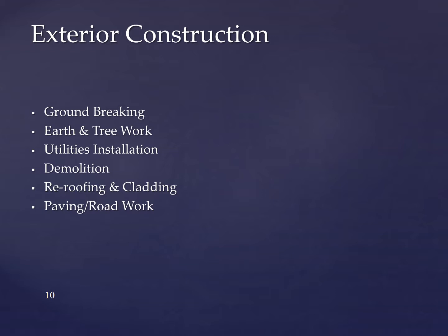There's a rule out there that you're not meant to do work within so many feet of intakes. It's easy to forget, when we're doing work, to assess where the intakes are. This is a common issue, particularly for those of you who don't have a lot of property, or for that matter, are very densely built. These intakes sometimes can be in places you just don't recognize. You forget they're there. So exterior construction has to always be considered. You have to always look around, see the traffic patterns, the air patterns, maybe even the wind patterns when it comes to doing exterior construction.